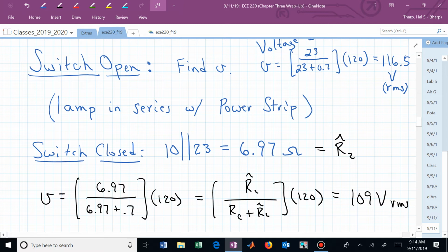What's happened when we switched the hot plate on to the voltage now seen by the lamp and the hot plate? They're the two cases. The voltage went down, didn't it? It decreased when we switched the hot plate on. What would you expect to maybe feel or see in that scenario? The light dims, doesn't it?